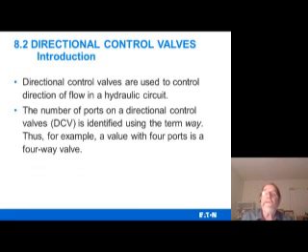Directional control valves are used to control the direction of flow in a hydraulic circuit. The number of ports on a directional control valve, called a DCV, is identified using the term way. Thus, for example, a valve with 4 ports is a 4-way valve.